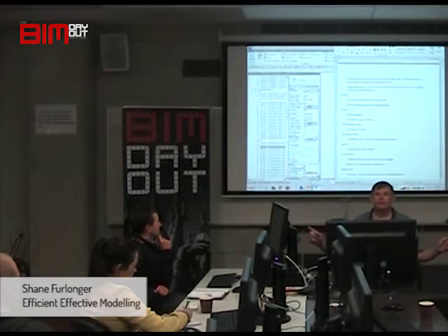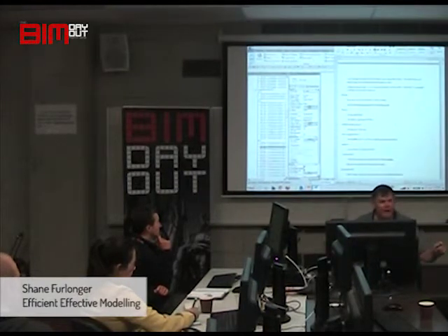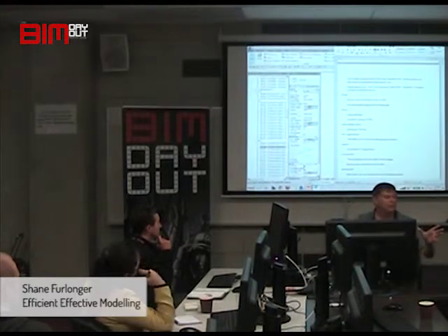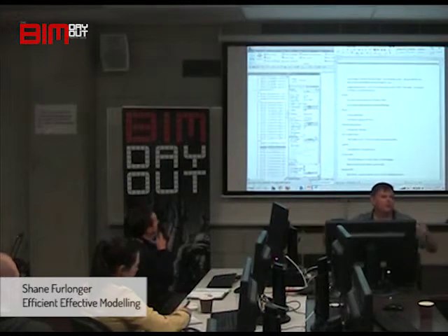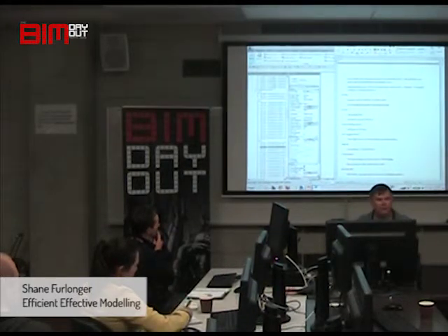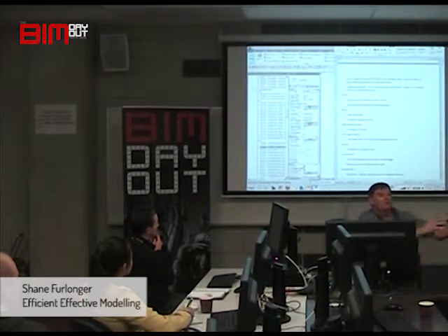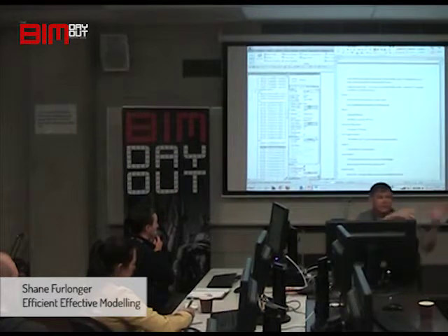Assemblies. Anybody used assemblies? No? You're making an apartment building and you've got the same apartment type in several places in the building. Yeah? Easiest thing to do, create a group out of those walls, copy them around the building to make that way if you've got to adjust those internal walls, all you've got to do is edit that one group and adjust all of them. Really good.